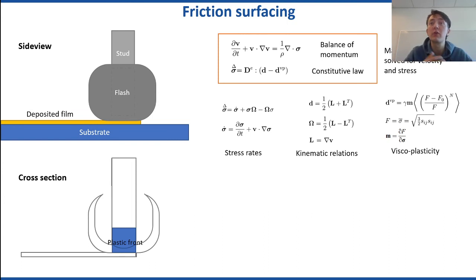And as it's moving through, it's developing stresses, and these stresses should be high enough to produce a plastic flow, and then it will flow out to different sides, either at the bottom or on the left, whatever would happen in reality, hopefully. So now we have an Eulerian perspective, even though we're dealing with a solid mechanics problem, right? So that is, I think, a very interesting example of why the theory that we're discussing in this class extends beyond pure fluid mechanics.